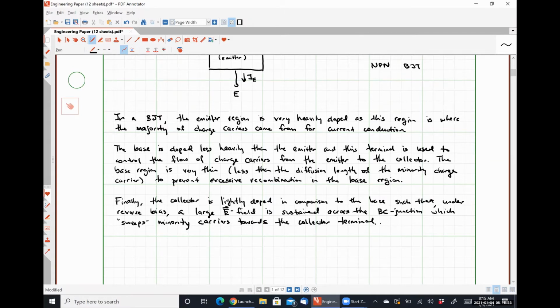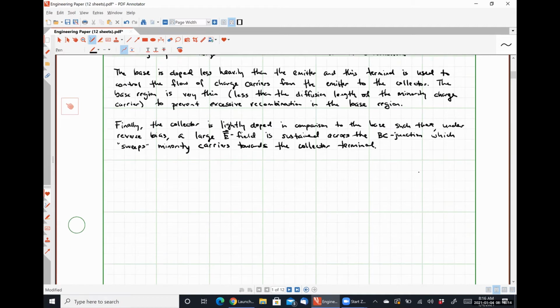Okay, so in a nutshell, then, what we have is an emitter, which in an NPN transistor supplies a whole bunch of electrons. And we have a base, which is supplying holes into the mix as well. And then we have a collector, which winds up collecting most of the electrons, and that's what's responsible for current flow through this device. But those conditions, the current that's flowing, are all dependent on the terminal voltages that we apply. So I want to make a simple table here. And this is all valid for an NPN transistor specifically.